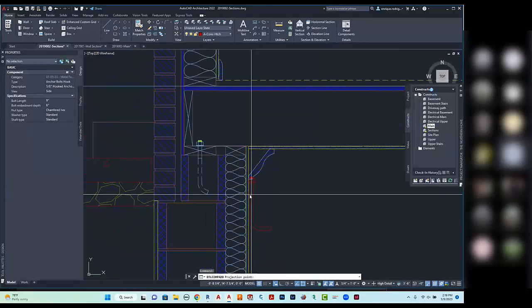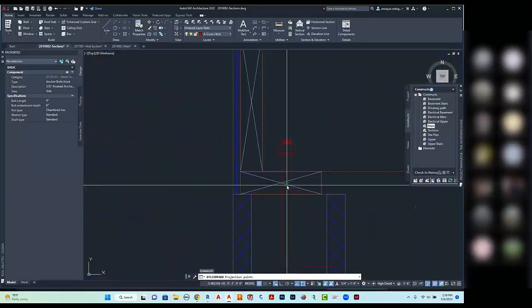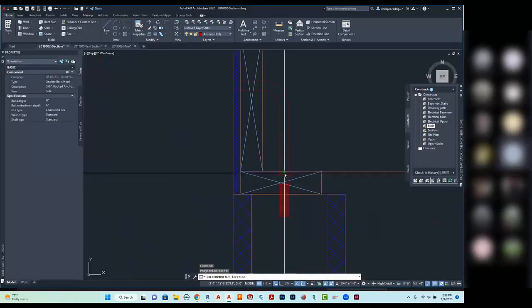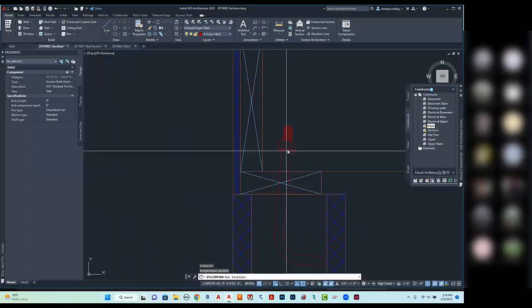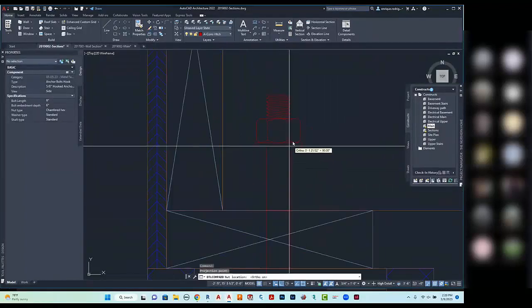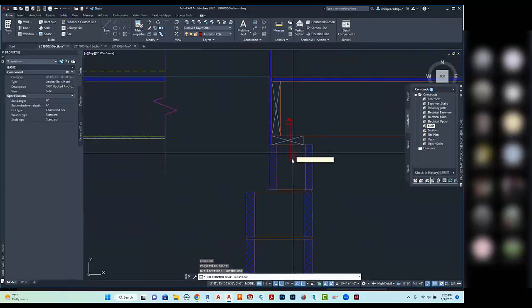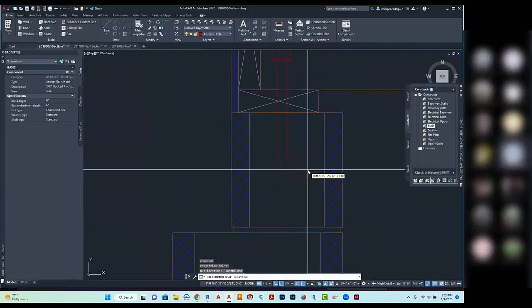and insert the component. Now this one has a couple of motions to it that you're going to need to do. Number one is I'm going to put my ortho back on. And I'm going to move the nut a little bit higher, right in here. And then I'm just going to give it a little bit more of a hook till it's almost vertical.